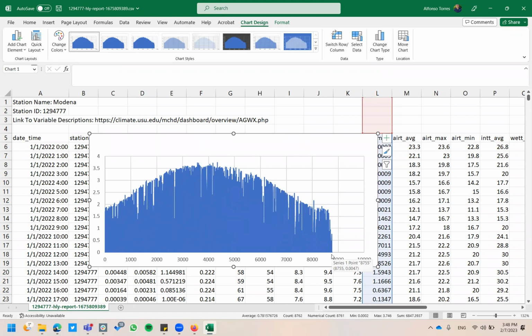What we're doing right now is called QA/QC, quality assurance, quality control of the data. Remember, we are responsible for what data we use to calculate ET. The Utah Climate Center does a really nice job keeping these clean, but I've seen data where we have negative solar radiation. So before putting the data in, we always have to check it out.